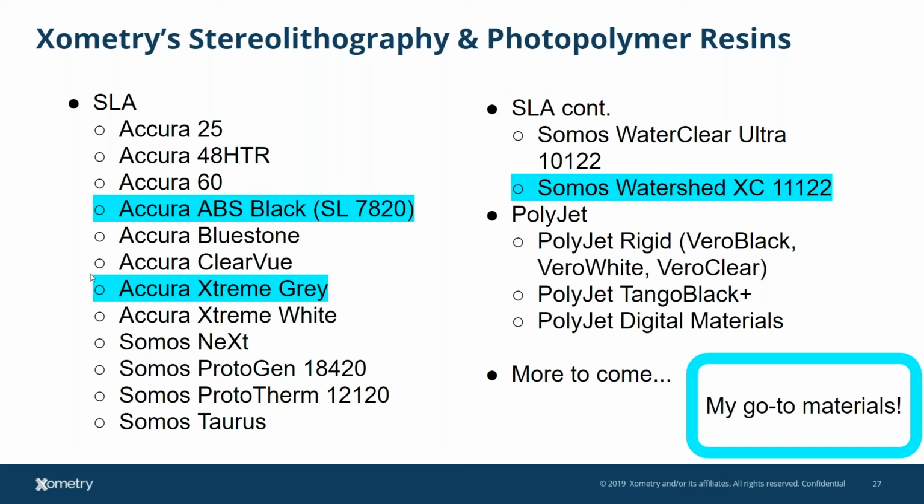Just understand that over time, clips and other features can wear out or snap on you. It's just the nature of photopolymers that this happens over time. So it has a shorter term value than a thermoplastic may have.